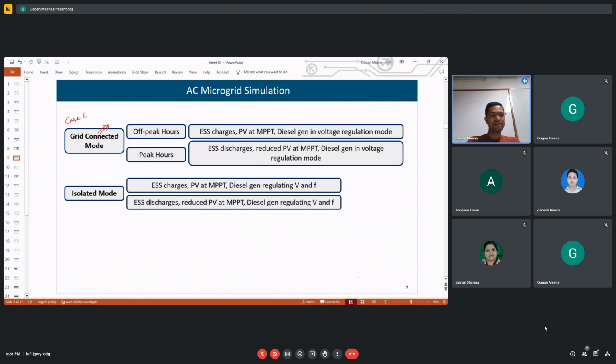on other phases. So if train is not there on one track or even on 2-3 tracks, and it is there in some other track, then there is naturally imbalance there. To reduce that unbalance, they also do transposition. After a few meters, they will interchange the ABC phases, so that unbalance is reduced.